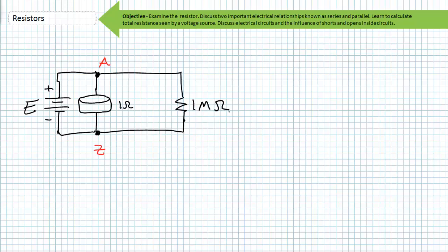This new resistor, however, is not another 100 ohm resistor, but rather a 1 mega ohm resistor, i.e. an extremely large resistance. This extremely large resistance could be symbolized by an extremely long, narrow, and obstacle-laden path. Yes, this single path is high resistance, but what have I done to the total resistance seen by the source? What I've done is I've added yet another path, and I've reduced the total resistance yet again.